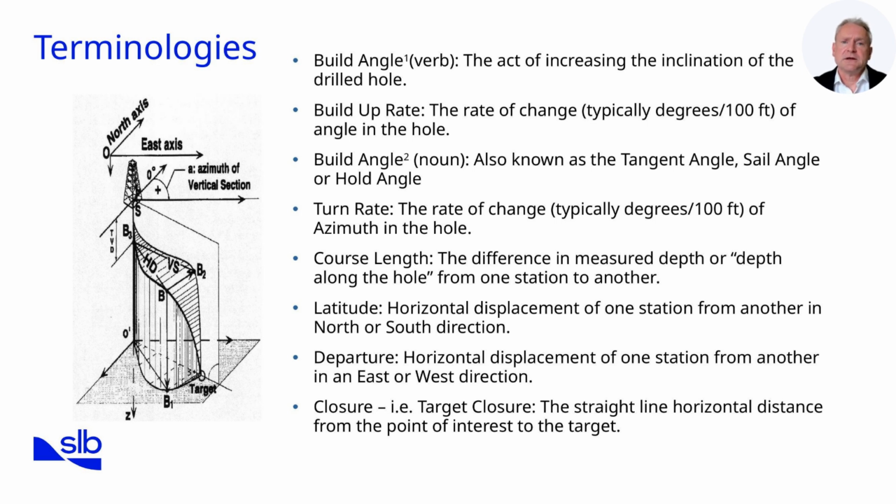The process of changing the angle of the wellbore from vertical to a desired inclination is known as building angle. This process involves specific downhole tools such as steerable motors or rotary steerable systems, RSS, along with real-time measurements of inclination and azimuth to guide the trajectory.